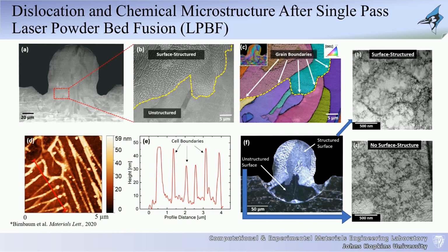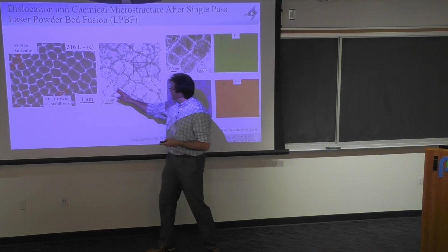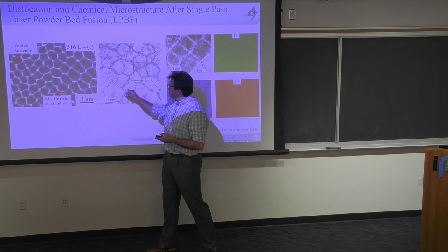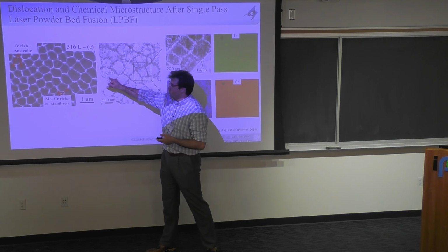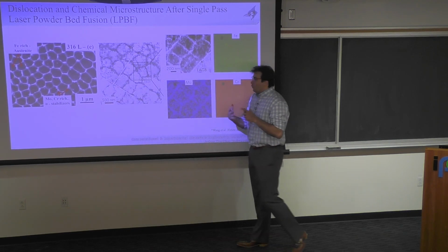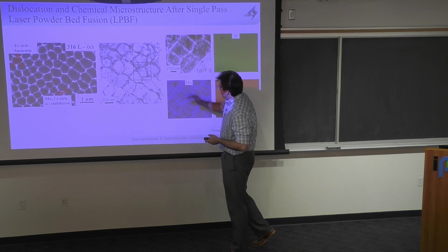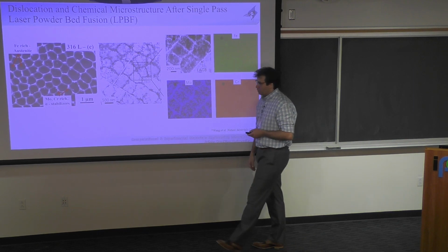So actually our collaborators from the Navy came to us and said, okay, we understand that these are unique structures. We don't understand why they formed. A couple of things that I actually missed to say, and it's not entirely clear here with the color: these dislocation walls, these cells, typically have walls that are aligned along particular directions, which are 100 directions. Why that was a puzzling question is that's where the molybdenum and the chrome walls are. They're, again, aligned along these same 100 directions.